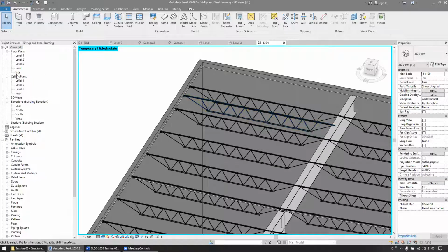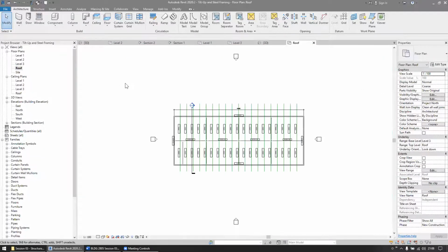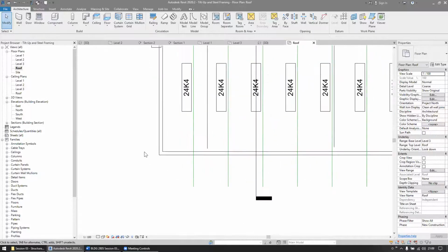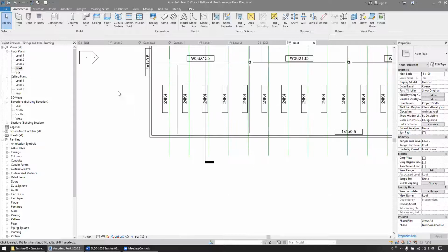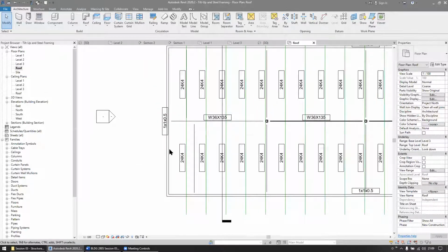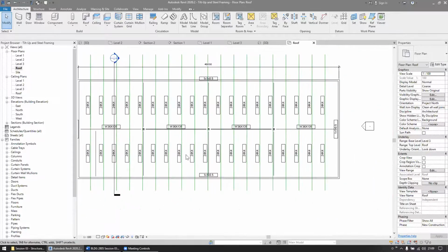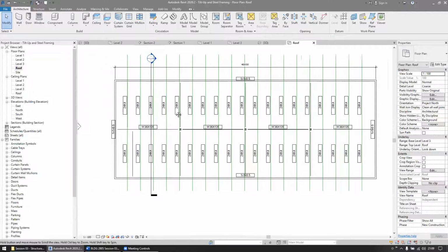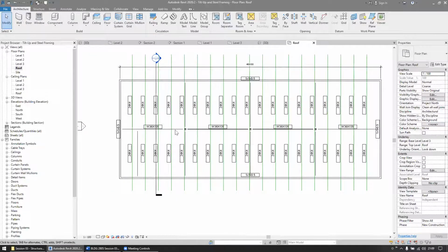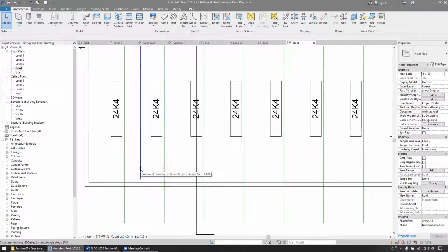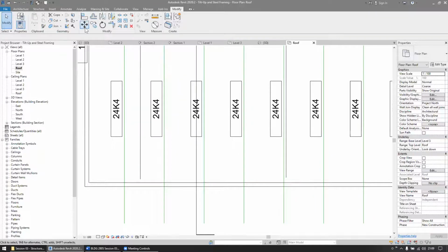So how do I deal with that? Well, in the roof plan, I've drawn a bunch of detail lines. You folks can see these detail lines in green here. Those are what I use to align my roof joists that I drew in manually. So here's the one that I just added. And I'll use the align command. Where is the align command? Go away, zoom interface, you're in my way. Modify, there's align.